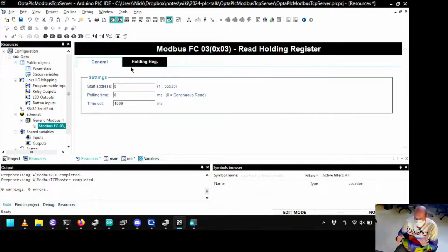Additionally, the standard variable size in Modbus, either Modbus, is 16 bits wide. So when you want something larger like a 32-bit integer or 32-bit floating point, you will use sequential addresses. So a 32-bit floating point will be 2 addresses, or a 64-bit floating point will be 4 addresses. And there's some compatibility issues there with getting the addresses incremented in the right order to go back into a number that make that kind of thing frustrating. So if you're trying to be compatible with other devices, that can get in your way. But if you're staying in the same family, they all talk in the same byte order, just like network byte order.